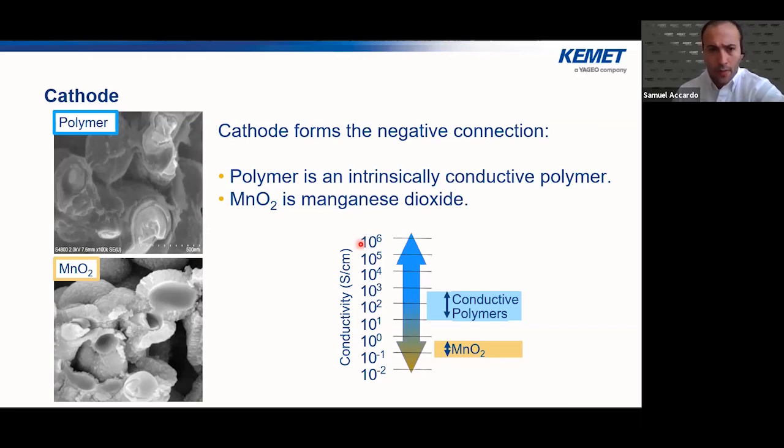But there's one additional thing that we have to look at when selecting the cathode itself, and that is its ability to form a non-conductive plug in the dielectric. So with KEMET and with other manufacturers, we all manufacture tantalum capacitors with faults in the dielectric. It's just how they're manufactured, and the ability of the cathode to essentially go through joule heating, which is taking the part and heating up, for instance, the MnO2 to a certain temperature so that it becomes Mn2O3 and forms a plug. So its ability to form a plug and lower the leakage current of the device is also very important.